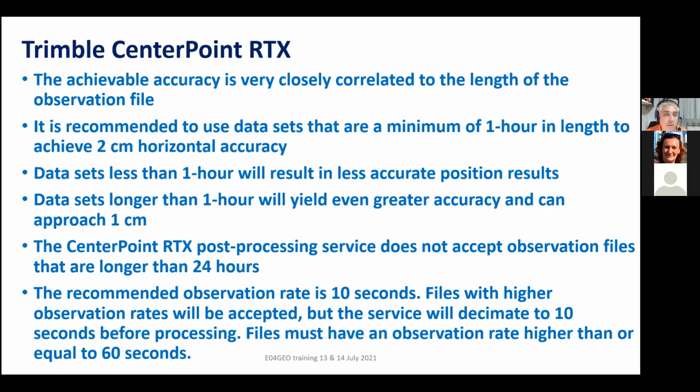What about a logging rate? So the recommended observation rate is 10 seconds. Files with higher observation rates, namely 1 second, 2 seconds, 5 seconds, will be accepted, but the service will decimate to 10 seconds before processing.